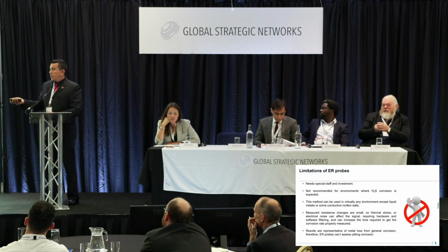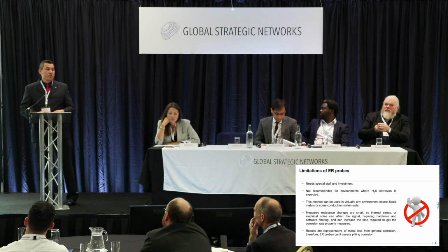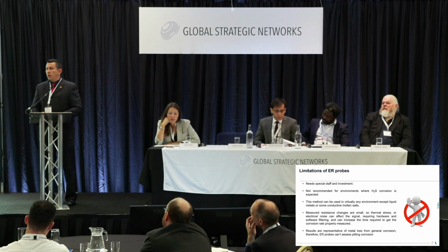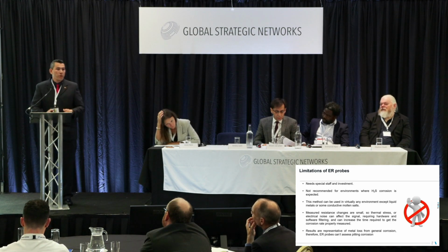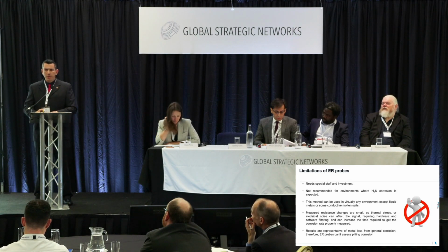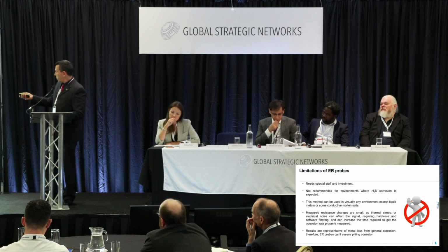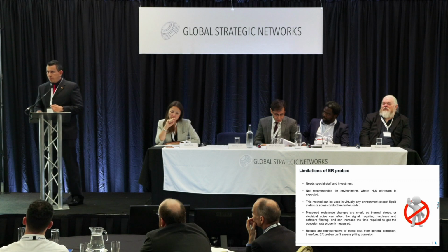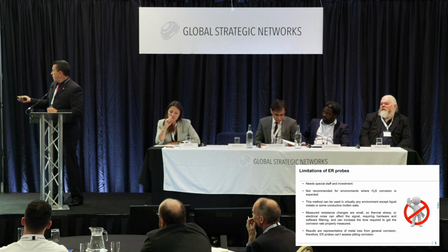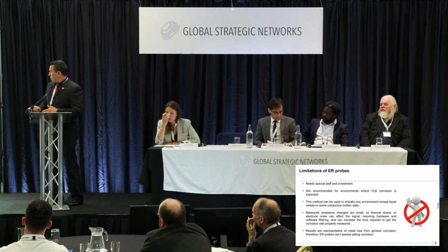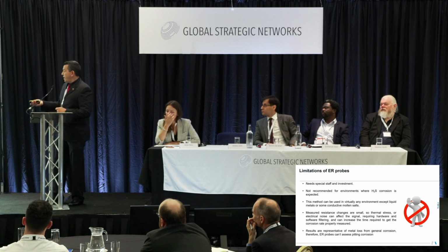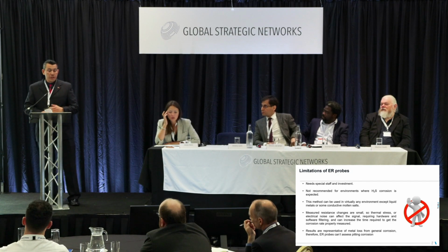Disadvantages. You need special staff and investment because the equipment is more costly than corrosion coupons. And as I said at the beginning, because of lack of knowledge and personnel with expertise, some operators are not using them. So you need to invest in your personnel to be able to have useful information. They are not recommended where you have H2S corrosion, as I said, because of the iron sulfide formation. You can't use it in liquid metals or some conductive molten salts. It's susceptible to temperature changes.